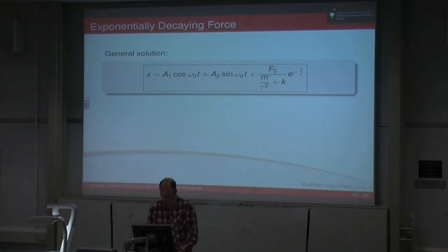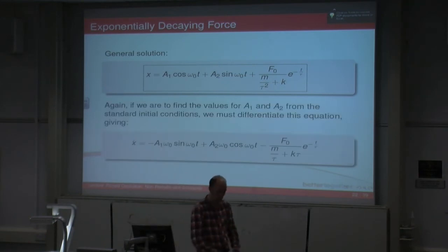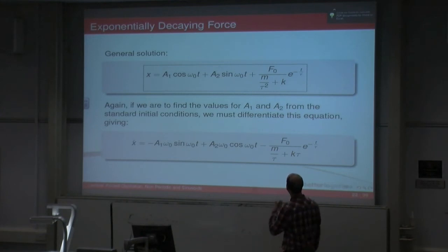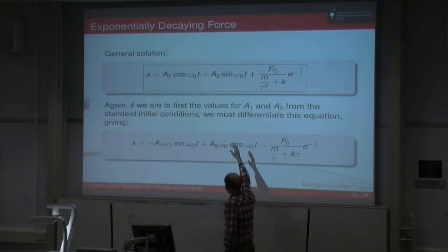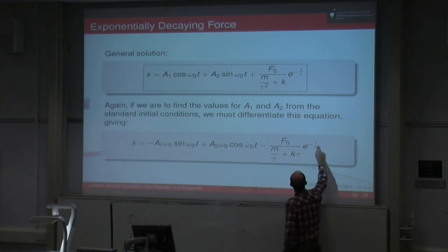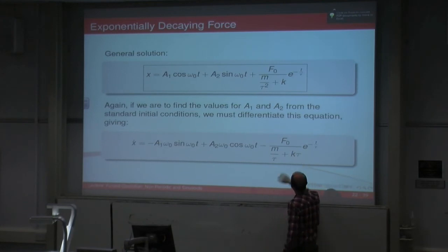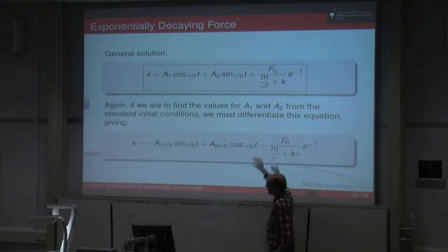And again, we have to find the derivative to solve for initial conditions. In this case, the same case, initial conditions of rest, when x naught is 0 and x dot naught is 0. That does the same thing when we take the derivative here. Again, when you take this derivative with respect to time, a minus 1 upon tau comes out, so you end up with this becoming tau instead of a tau squared, and then you have a tau on the bottom because you have minus 1 upon tau in front of that whole fraction.